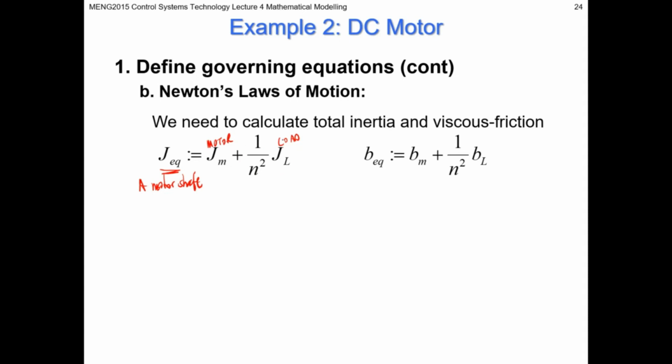That's the impact effectively of the inertia due to the gear ratio. So what this says practically is if you have a higher gear ratio, the way the inertia feels at the motor shaft is reduced, right? So if n equals 3, a 3-to-1 ratio on that transmission, then JEQ might be equivalent to Jm plus JL upon 9, right?